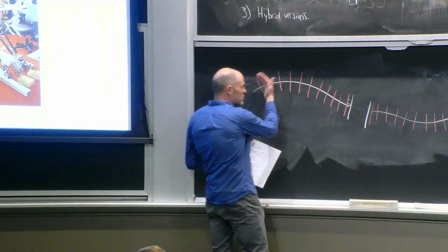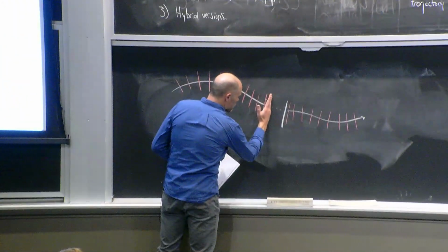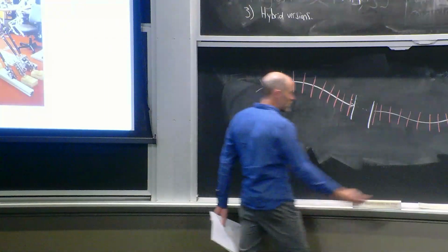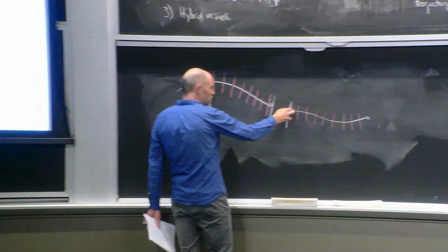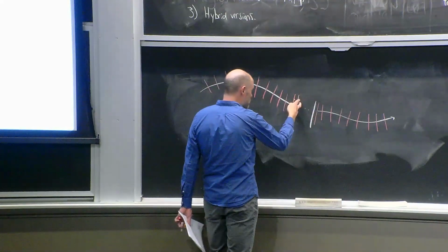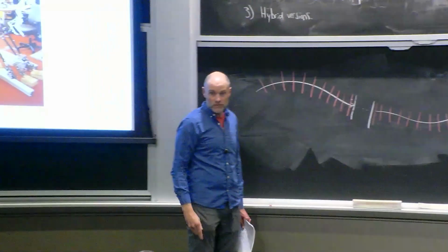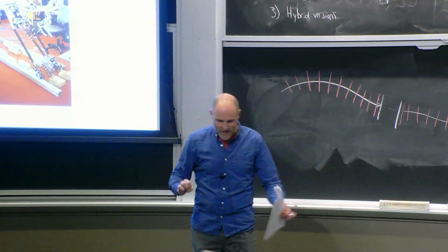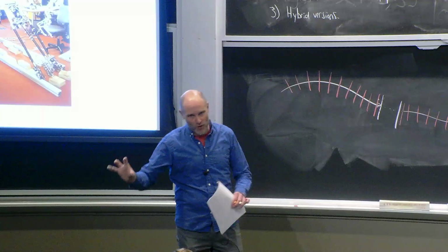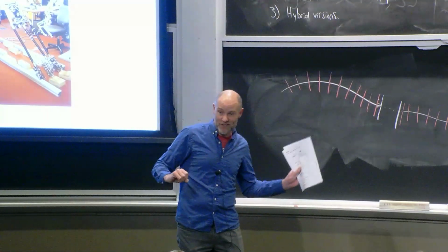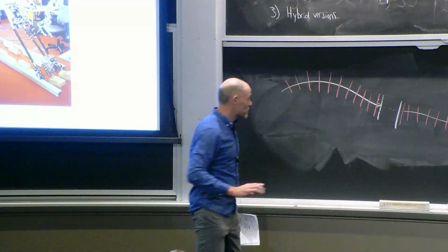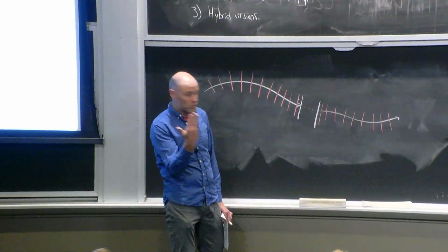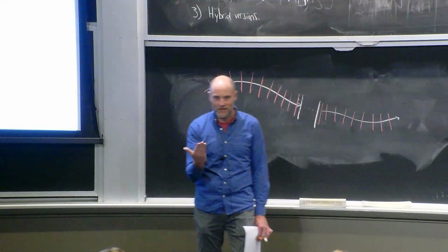Similarly with LQR, we can do the transverse LQR, and you take linearizations that try to line up with the surface of section, so that the time-varying dynamics can be evaluated with the continuous-time Riccati equation, a jump, the one step of the discrete Riccati difference equation, and then the continuous Riccati equation backwards in time. So I've been doing a dance between limit cycles and hybrid. They happen to play together algorithmically for two reasons. One is that walking robots are hybrid, so you have to do both. But the other, subtler reason is that some of the computational things that we do for limit cycles and orbital stability are also very natural for dealing with impacts, because you can restrict your attention orthogonal to the collision events.